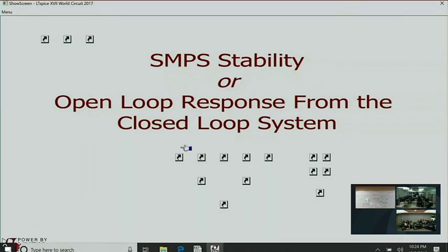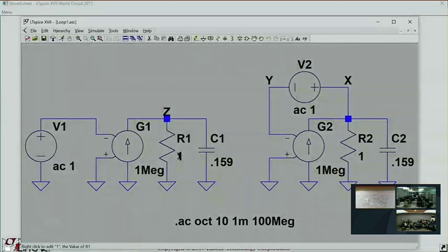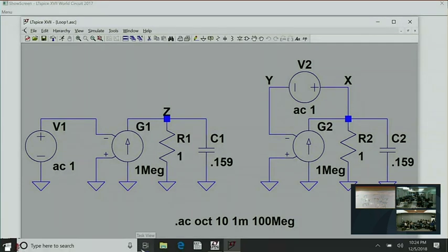So let's do it first for something like an op-amp. This is the simplest circuit I can contrive that has a transfer function nominally like an op-amp. Okay? This is a transconductance, which means that the input is a voltage and the output is a current. The coefficient of transconductance is 1 million. So if I put a microvolt here, times a million is 1 amp. So that's what that element does. I read out that amp with this 1 ohm resistor, so that I put a microvolt there, I get an amp, I get a volt. The DC gain is 1 million, nominally like an op-amp.